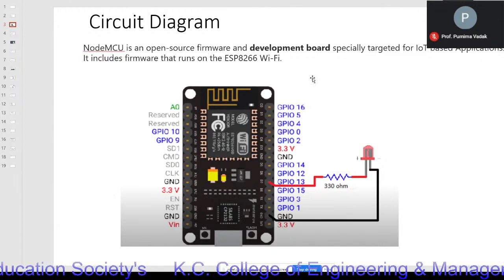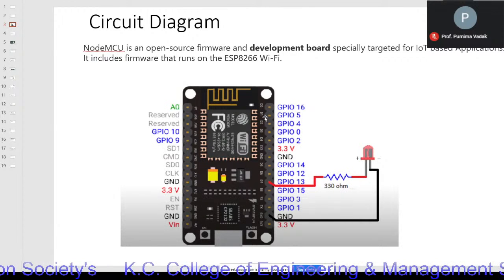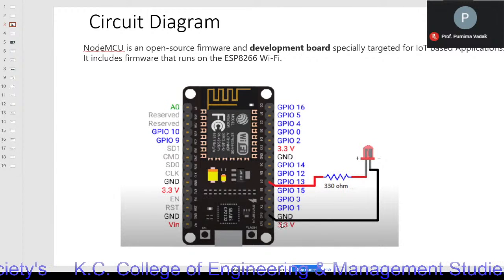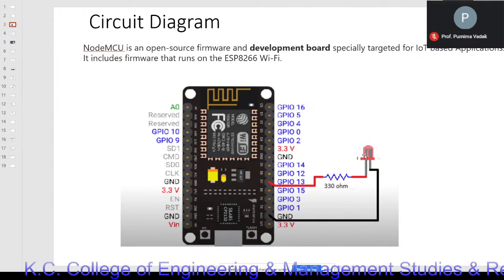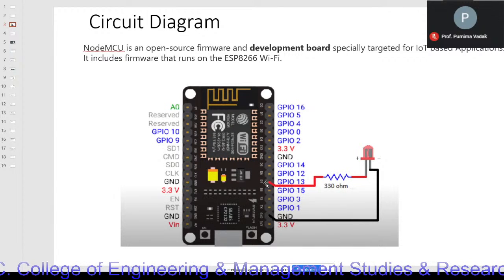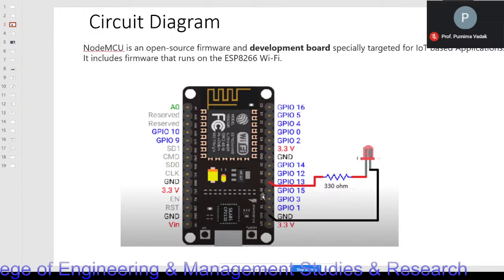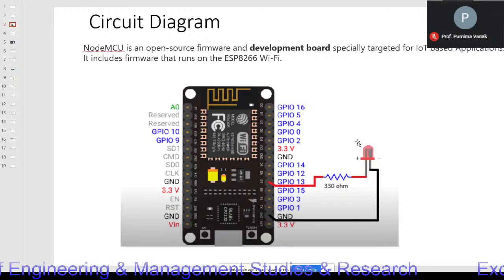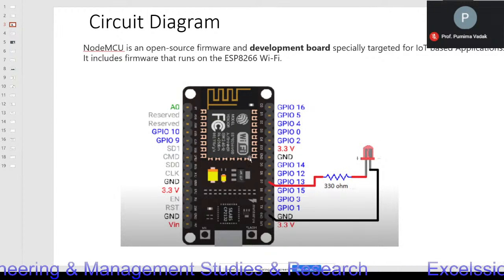Okay, and it's working similarly to the Arduino itself. This is the processor over here, some pins over here, ground, and so on. So here I'm going to add my LED bulb in any digital pin. I'm selecting D7 over here and another point as a ground pin. Regarding the LED bulb, what the resistor is and all those things, Purnima has already explained that. I'll simply connect that circuit with the LED.